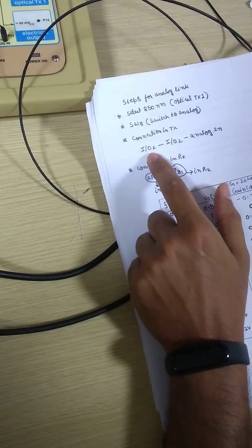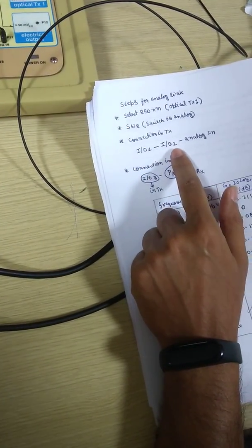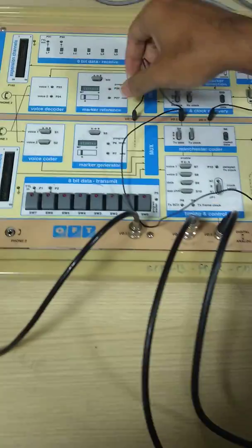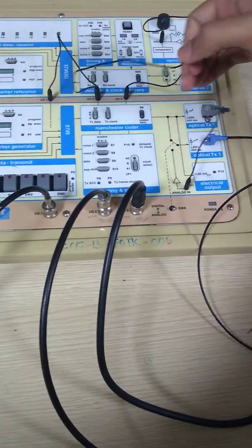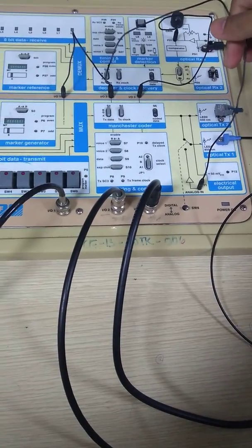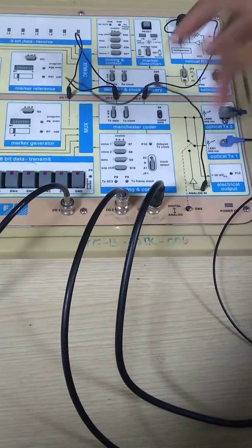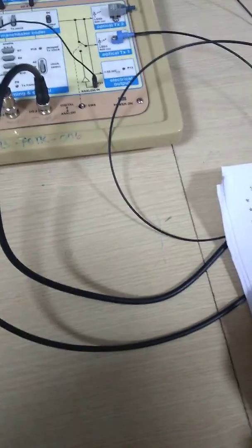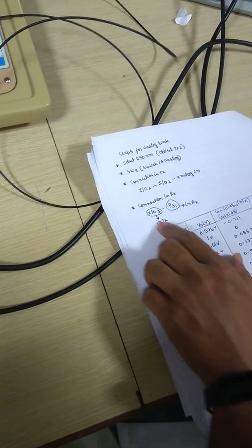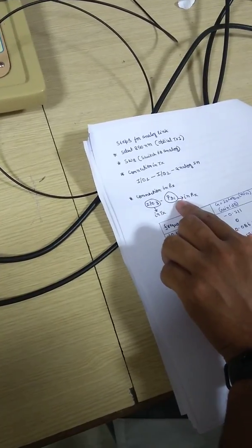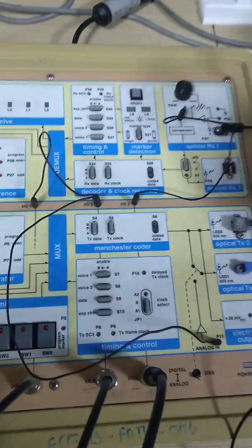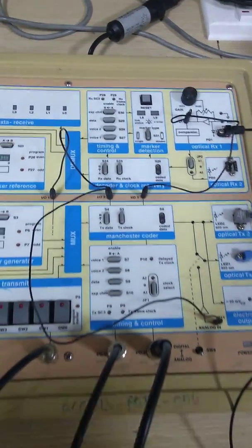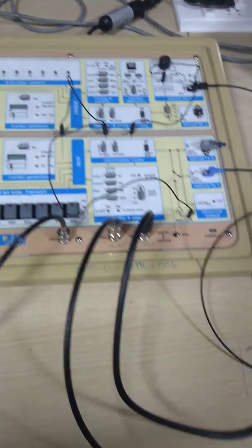The first connection that we'll make is IO1 to IO2 to analog in. So IO1 is connected to IO2, which is then connected to analog in. With this 3-terminal wire you'll have to use IO1 to IO2 and then IO2 to analog in. After that, you'll connect the transmitter part to the receiver part. For that, IO3 in the transmitter is connected to P31 in the receiver. Once you have made all the connections, most of it is done.